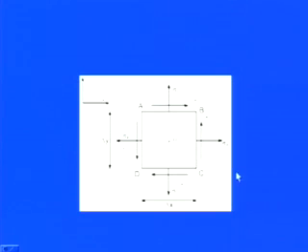If we are talking about this, we have a unit cube which has a total width in x direction of delta x and a total width in y direction of delta y. If you are working in the x domain, we have 2 components. One is sigma x, which is the normal stress component. The other is tau xy, in the downward direction, or tau xy in the upward direction, because x is the domain and y is the direction, upward as well as downward.